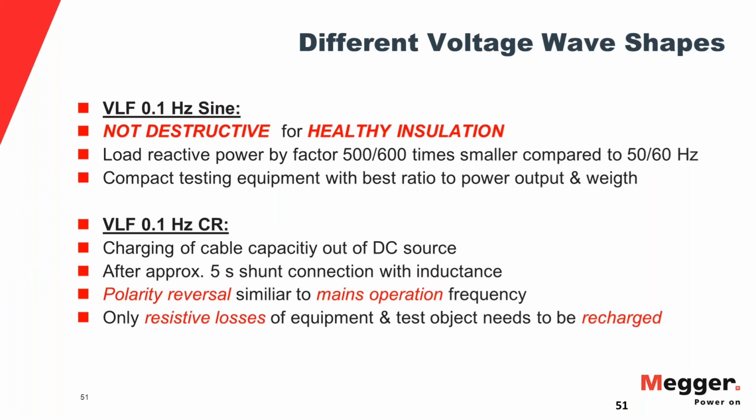The problem really is that originally PD testing was not done with VLF, and then the market went to this, demanded it or asked the manufacturers, and then as a second development, the VLF waveforms came into play. And there's two. Again, I want to call back to the webinar in December. The first one, the original, was the cosine rectangular, invented by Eckhard Lehfeld at HDW in Kiel. And that was the cosine rectangular VLF.